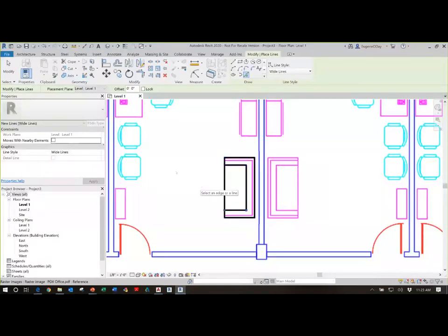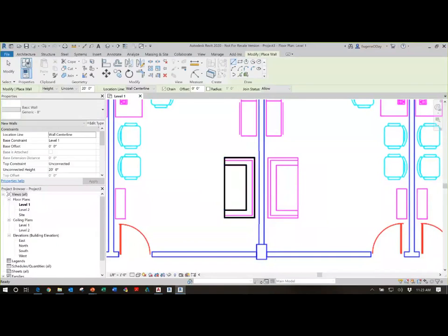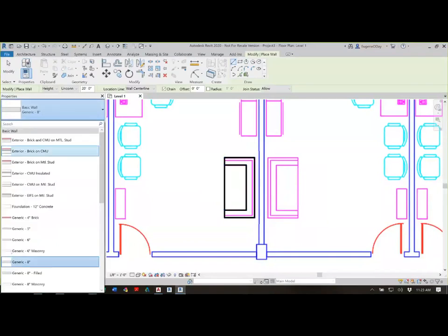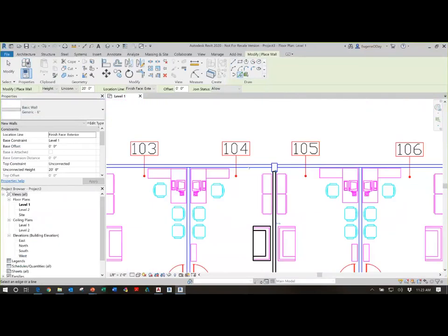Take it a step further and add some modeling geometry. And pop over here to the Architecture tab, grab Walls. I want to do a 6-inch generic wall. I want to use the finish face, or one of the faces I should say. And I'm going to use the Pick tool. And then all I need to do is pick on that wall. And I've just drawn that wall. So I'm basically tracing on top. And if I pick wrong, of course, I could always just flip that.